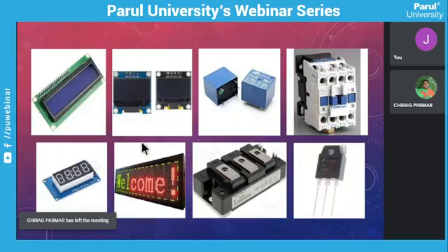Coming to the displays, we get an LCD. It is well known, and you may even have used it. The first type of display is the LCD. The second type of display is the OLED display, which uses I2C communication to connect with the controller. We will discuss that in the communication section. Some LCDs also use I2C. I2C is applicable on both of these.